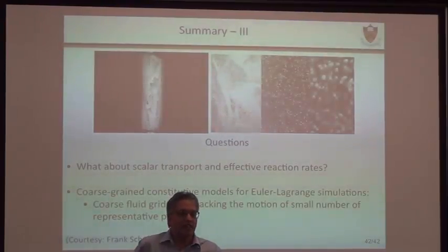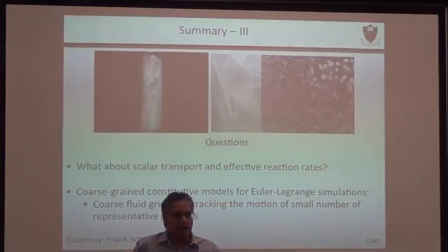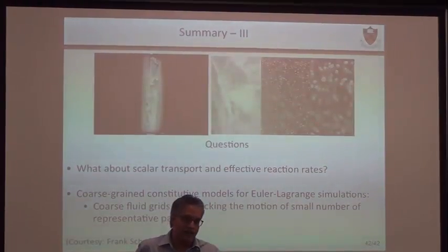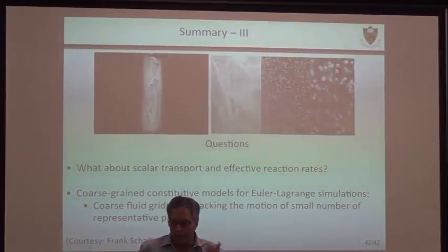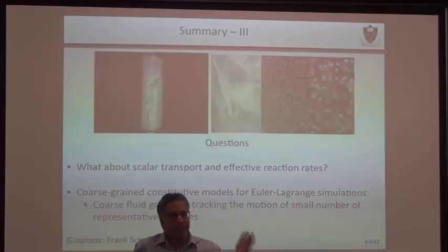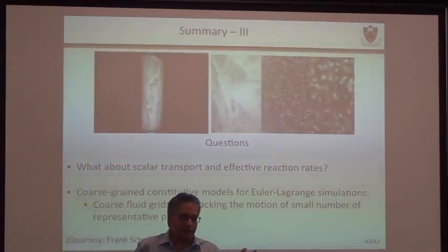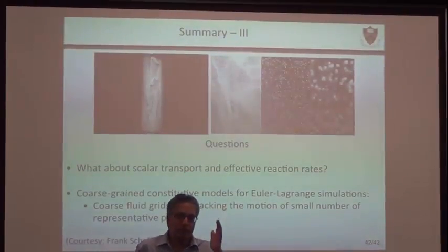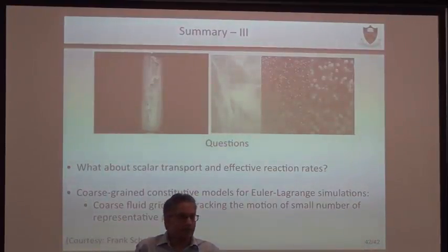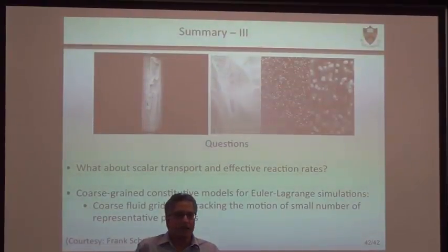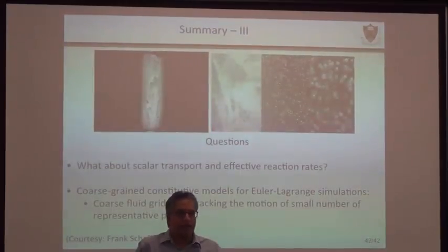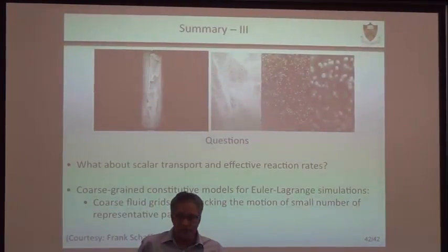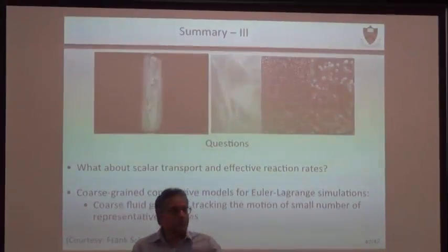So you have these non-idealities that come into play. How do you deal with all these non-idealities? The two-fluid model framework that I talked about becomes very cumbersome for those applications. So the field is drifting towards the Lagrangian simulation, where you still solve the fluid phase in a continuum fashion, but the particles are treated in a discrete fashion by using some approximation methods. It can be parcels, direct numerical simulation, or collision tracking. So there are many different scales of this, and that's where the field is evolving.